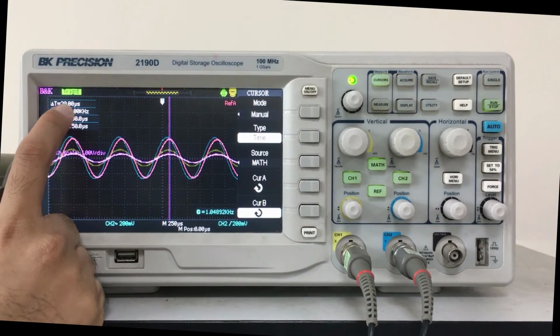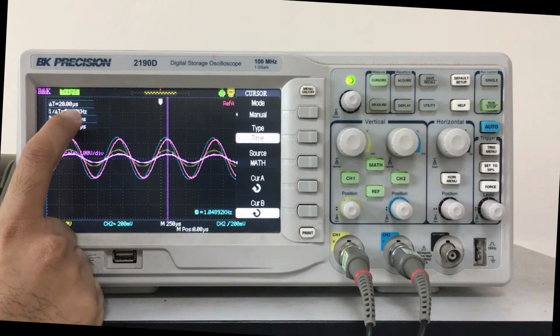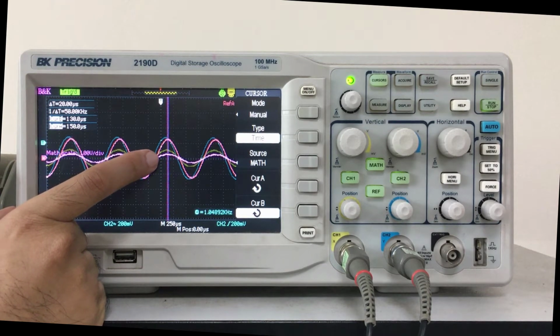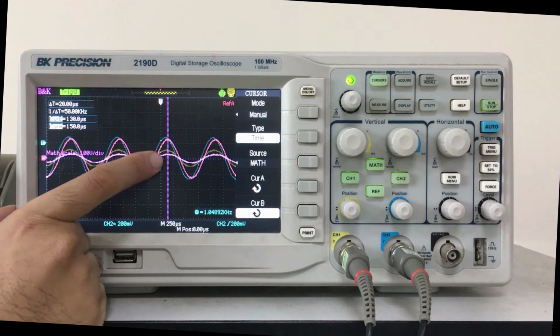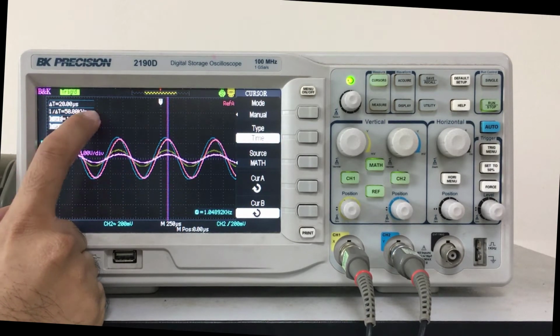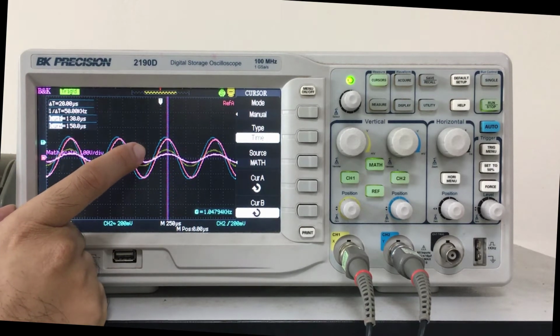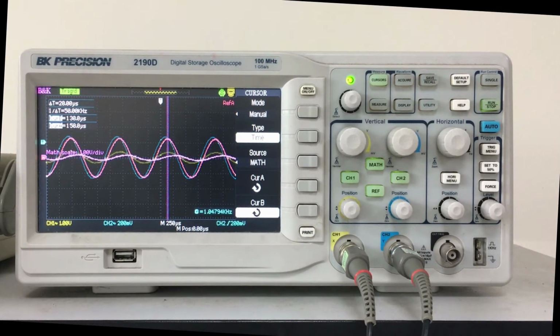So we see that the delta t is 20 microsecond. So the phase difference is 20 microsecond, and the blue signal is lagging. It's slightly behind the source voltage. So we will record this as 20 microsecond, and since it is lagging, the sign should be minus. We record 20 microsecond as time delay. It's lagging, so the symbol is minus. Using the calculator, we find that the angle is 7.2 degree.